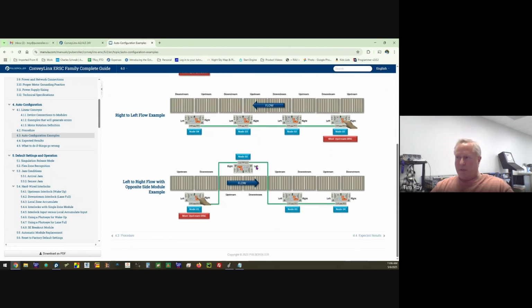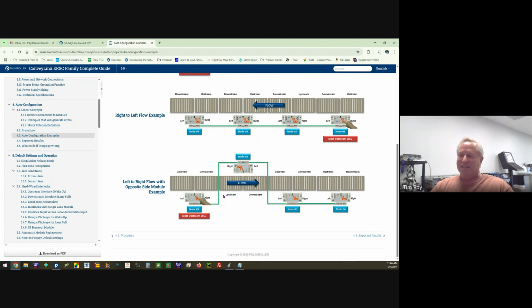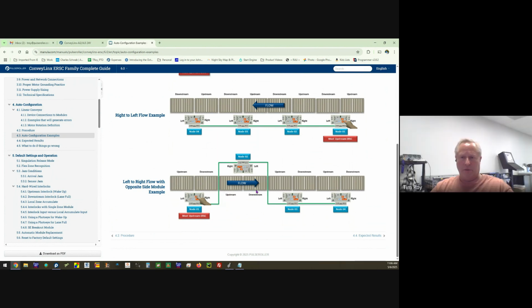And this little special case here, this is more integrator stuff. You get to the job site and someone forgot to put this big column on the drawing. You could leave this card behind the column, but that's really going to make the maintenance guys mad if they have to fix it or replace it. So the best thing is to put it on this side. You can leave your motors here. You don't have to take your motors out and redo the whole conveyor. It may require an extension cable to make the cable long enough.